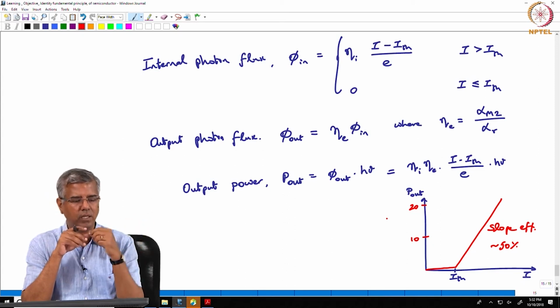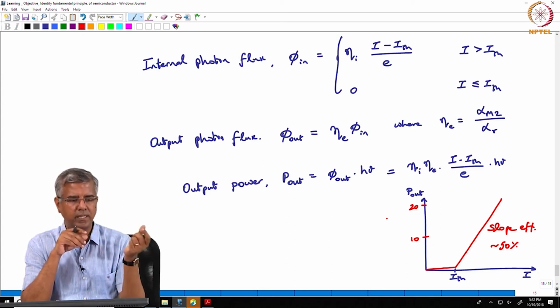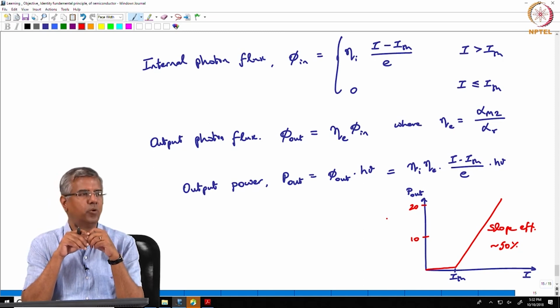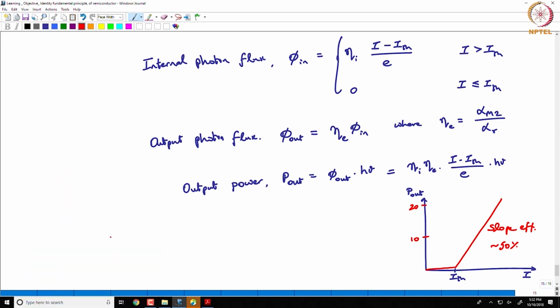First of all, the semiconductor lasers that we have in the lab are all multi-mode lasers, what are called broad stripe lasers. So, you have a fairly large region over which this emission happens, a fairly broad aperture over which this emission happens.